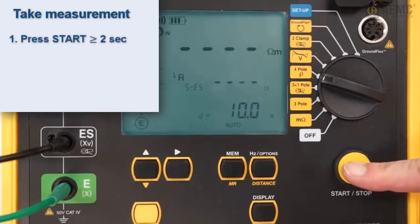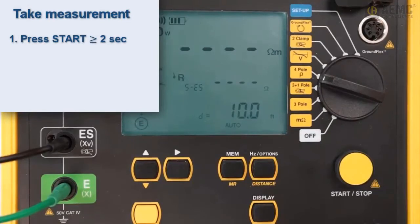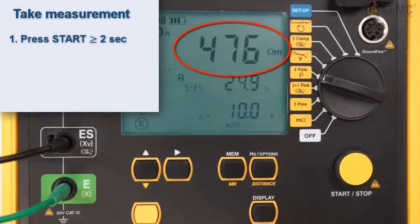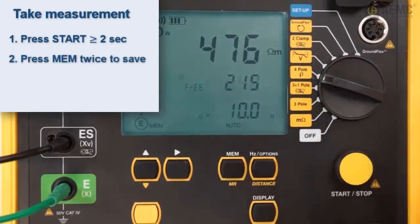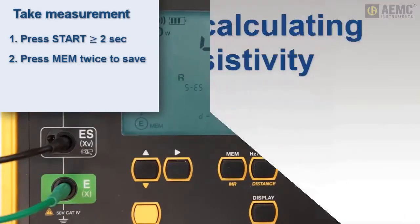To do this, press the start button and hold it down for at least 2 seconds. After a few moments, the resistivity reading appears displayed in ohm meters. The resistance of the soil between the 2 potential electrodes is also displayed, shown in ohms. To save the measurement in the instrument's memory, press the mem button twice. This saves the reading, along with the date and time the reading was taken. This stored record can later be displayed on the instrument screen and downloaded to a computer using DataView for further analysis.